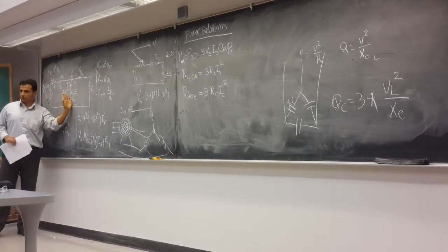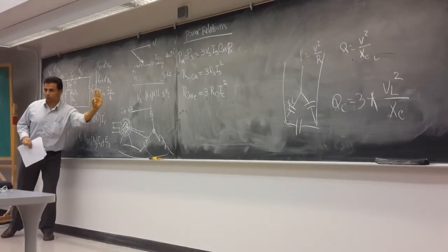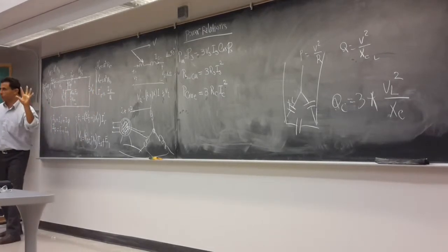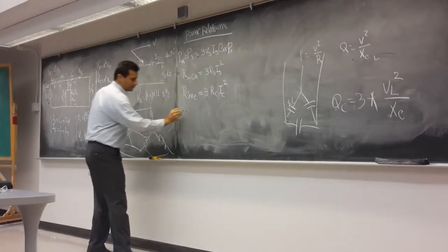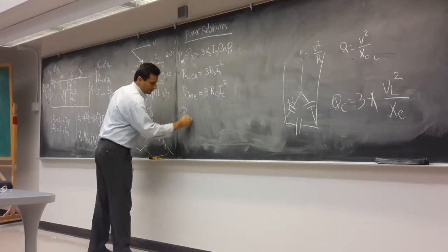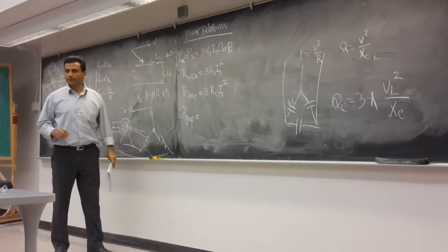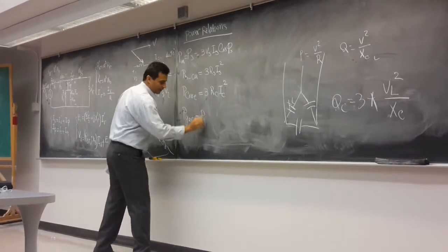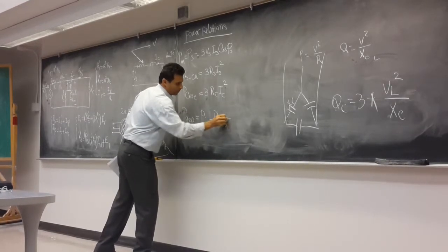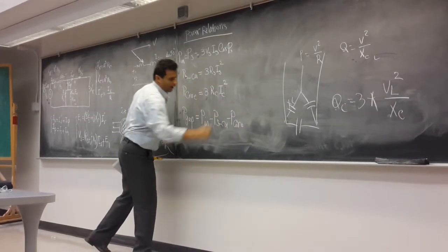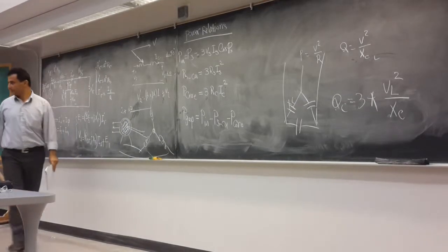We finished the stator, going to the rotor, right? This is the power going through the air gap to the rotor. We call it P gap. How much is the P gap? It's P in minus P SCU minus P core, right? That's correct.